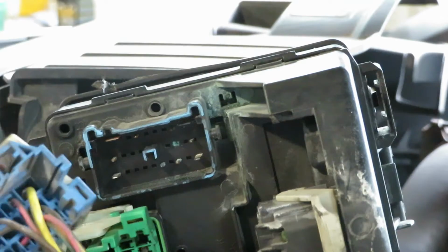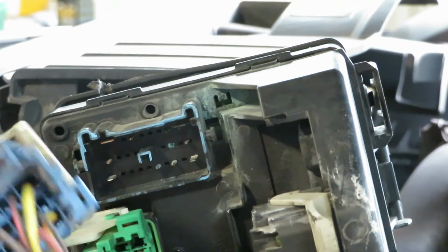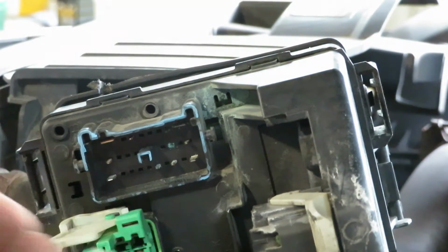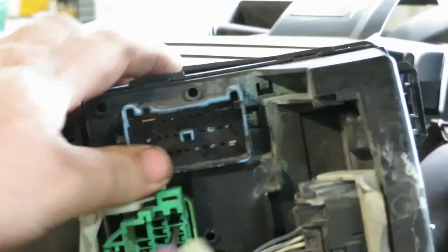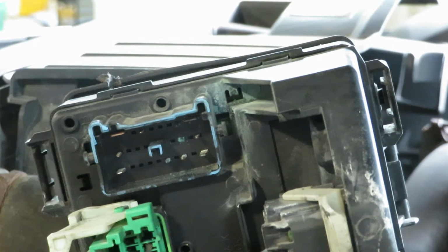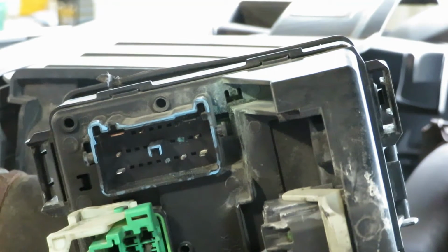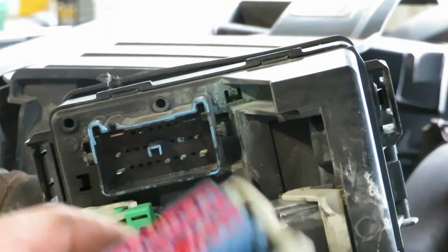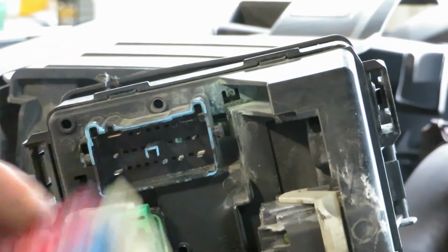So this connector's corroded and has to be replaced, and the TIPM is corroded internally and needs to be replaced. Now if it was just an internal relay, I have found a place called CCR Technologies that can rebuild these for a reasonable price, but if a pin or something's rotted off, then there's not much they can do about it, I guess. I've tried in the past, and I believe they're not able to. So we've got to put a new connector on here and replace the TIPM.